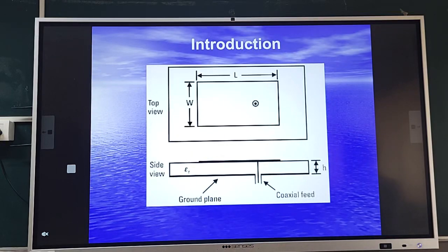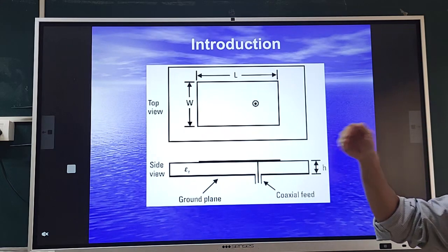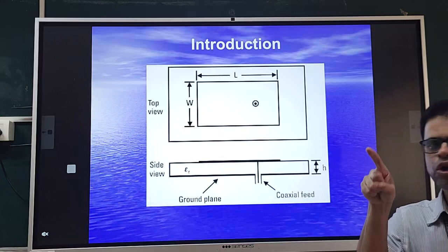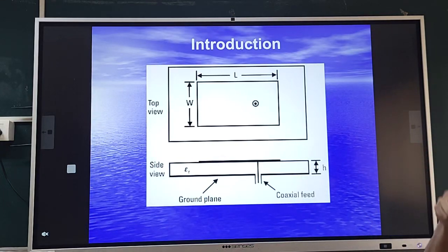For that, I need to ensure that my antenna parameters are independent of any variation which is expected in these substrate parameters. For that, air suspended substrate provides the solution. So air suspended design not only provides you the option of realizing a low cost solution, but it also improves, this line is very important, it also improves the reliability of antenna parameters against substrate parameter variations.